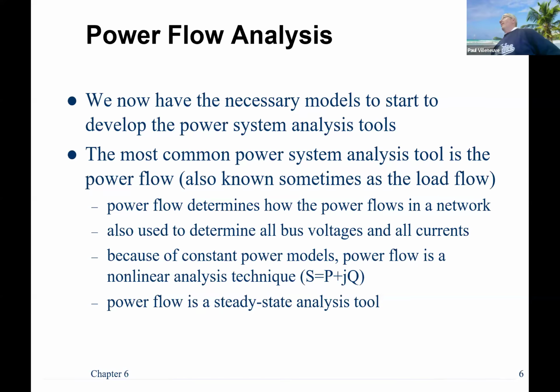But what makes this really difficult is our models tend to be nonlinear. What do I mean by that? Because S equals P plus jQ, it is not a linear relationship. So we actually have to solve our power flow using nonlinear analyses. And have you all done nonlinear analysis up to this point in your college careers? Laplace? No, that's linear. Almost everybody here has, they just don't realize it.